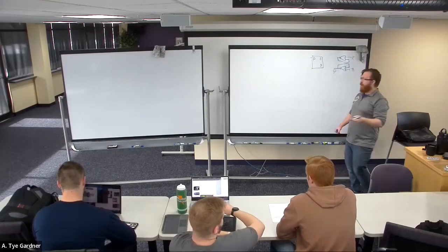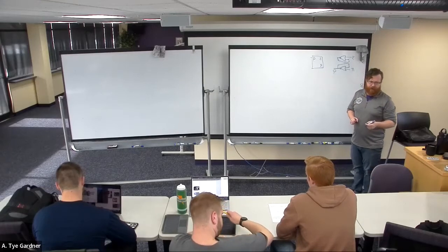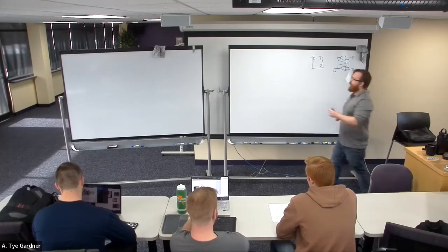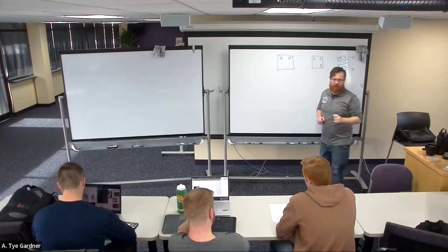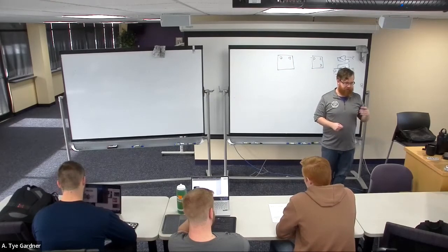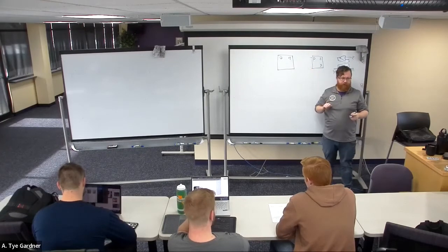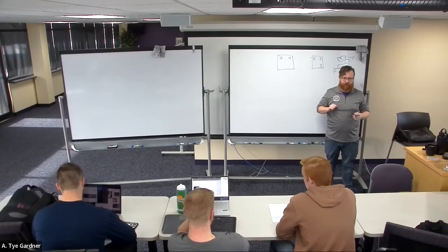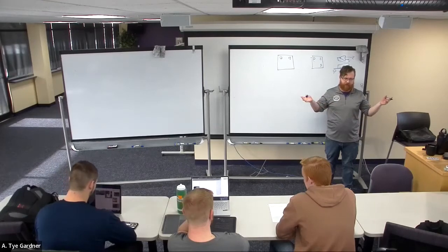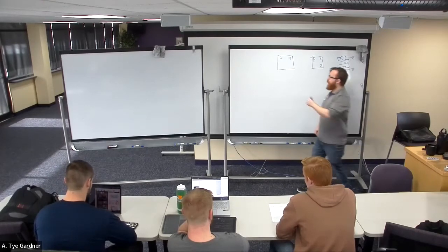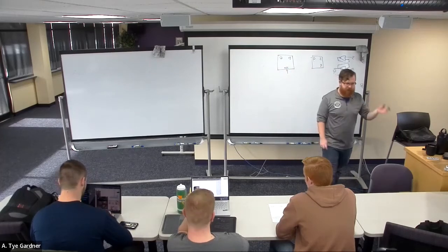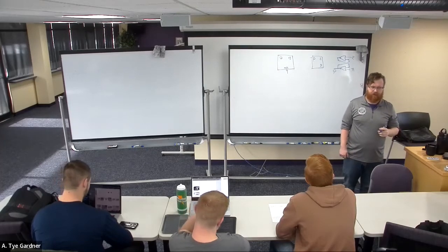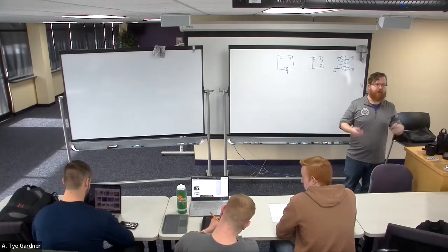And then we can combine the SR latch with a little bit of AND gate logic right at the input, and we can get a D latch. The D latch is something that just latches onto whatever the data value is, right? So if data is 1, it's 1, data 0, it's 0. It can optionally have something like, say, an active low reset that would reset it back to 0, regardless of what data is doing, power it down.